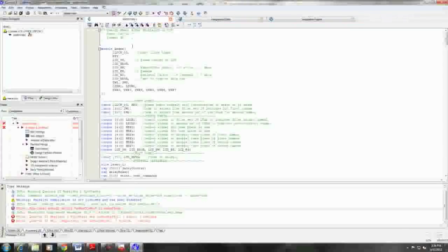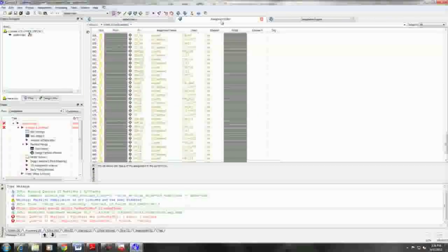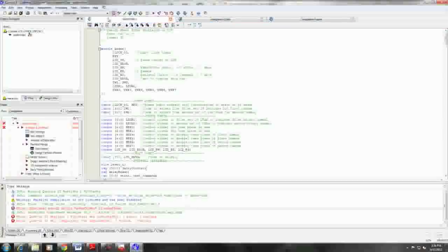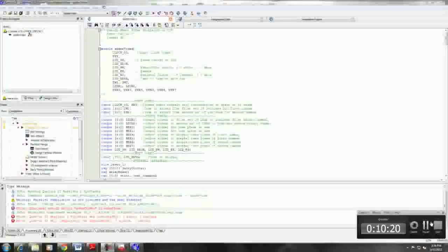And in compiling our design, we ran across an error, and that error was, as I mentioned to you, generated out of the top level entity not being defined. And this is a pretty common error when you are first getting started. We copy and pasted our code, but the module name was something different other than what the top level entity was. And so we just needed to go back in and redefine that. And now on the second go around, our code will hopefully compile.